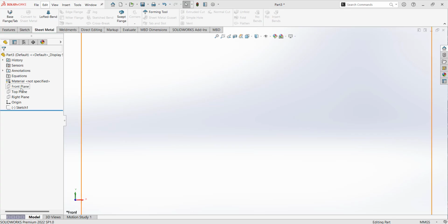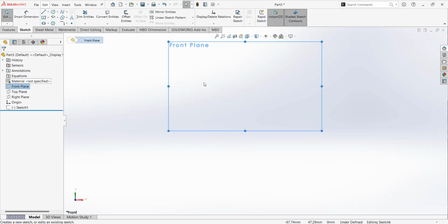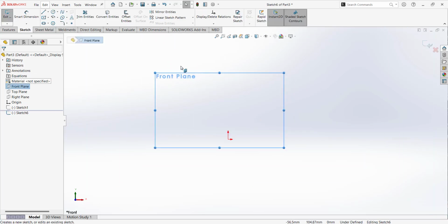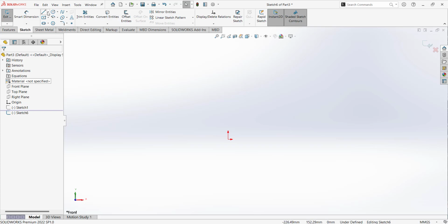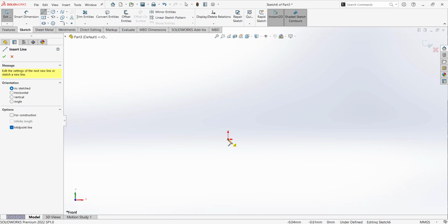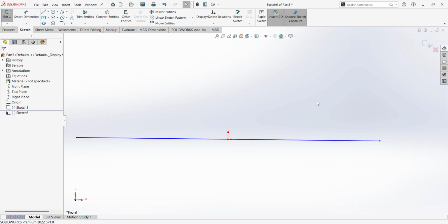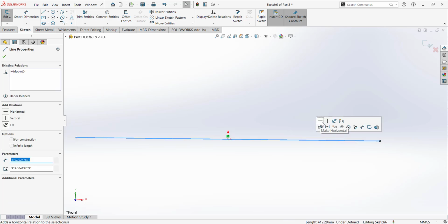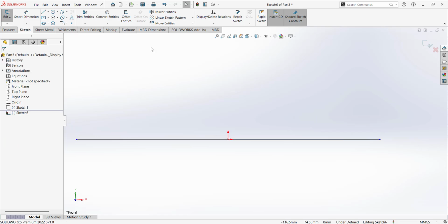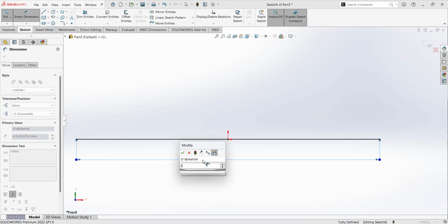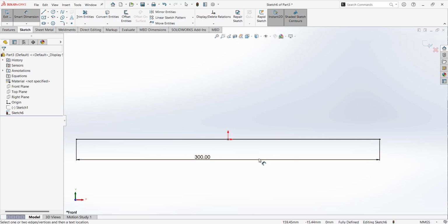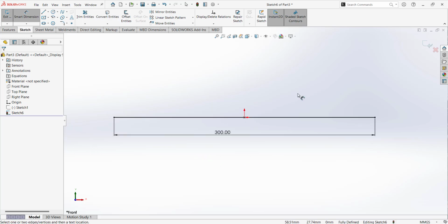Now we will start with a new file here. Select the sketch. We are going to make one panel in sheet metal. For that I'll make one base flange using midpoint line here. I am taking midpoint line because I want all the reference planes to come at center. That's why we are starting the part with center line only or midpoint line only. Say horizontal. I'll take this distance as 300 mm as I want the panel box width to be 300 mm.